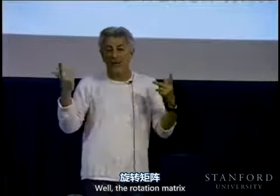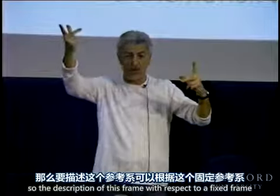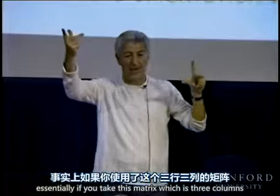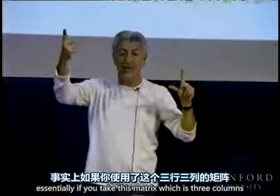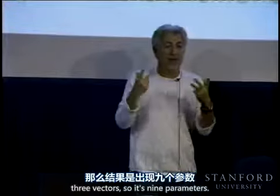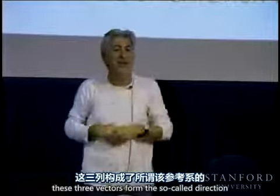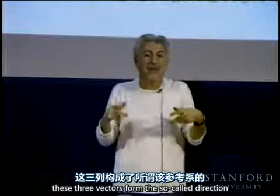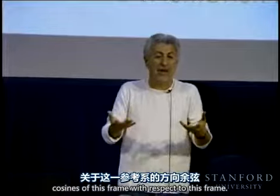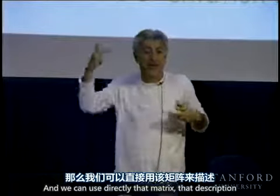Well, if you take this rotation matrix between 2 frames, so the description of this frame with respect to a fixed frame, essentially, this matrix is 3 columns of 3 vectors, so it's 9 parameters. These 3 vectors form the so-called direction cosines of this frame with respect to this frame. And we can use directly that matrix, that description.